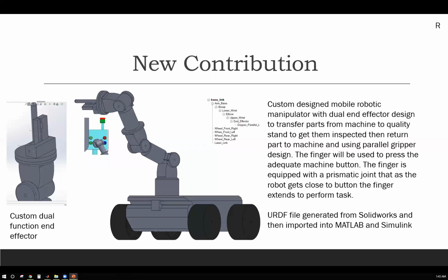The steps taken to reach the design shown here, at a high level, are identifying and understanding the environment that the robot is going to be functioning in, simulating that environment through CAD modeling, and then creating a robot in a CAD model environment that would reach all the points required to do its task without being in a singularity position.